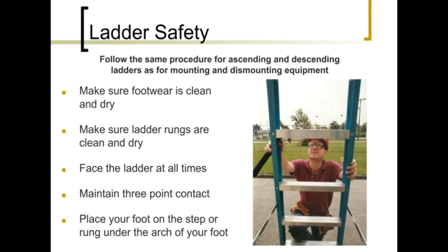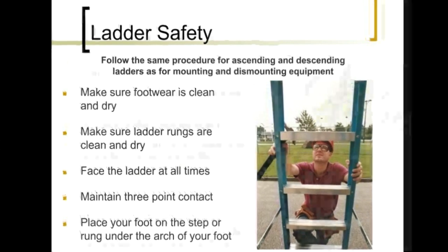Some notes about ladder safety. Follow the same procedure for ascending and descending ladders as for mounting and dismounting equipment. Make sure your footwear is clean and dry. Make sure ladder rungs are clean and dry. Face the ladder at all times. Maintain 3 points of contact. Place your foot on the step or rung under the arch of your foot.